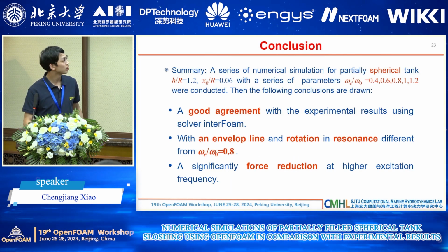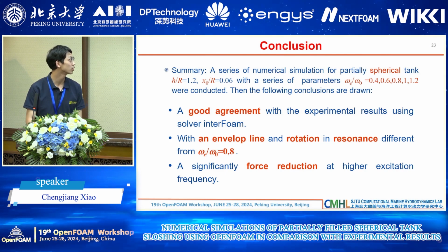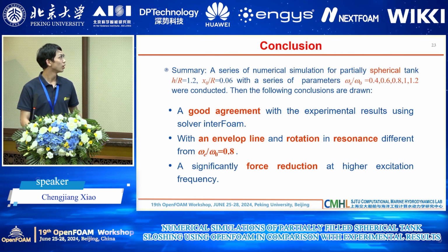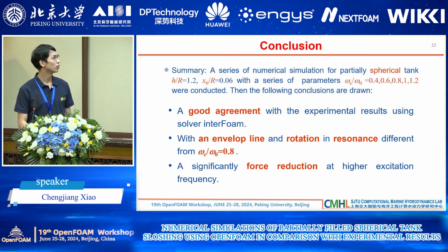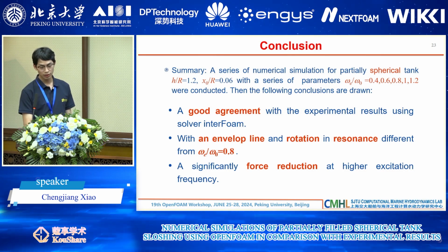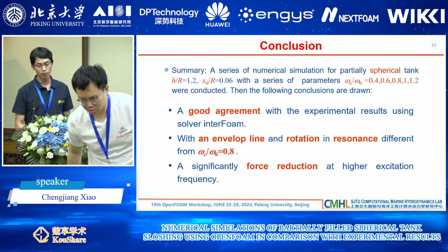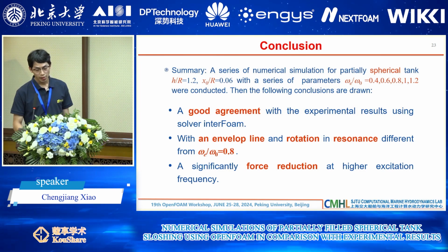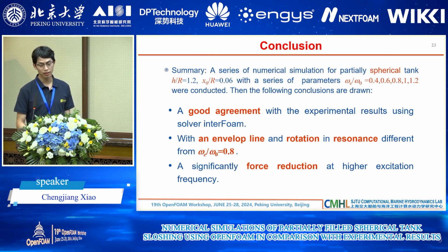Now, in summary, a series of numerical simulations of a partially filled spherical tank with different parameters omega e to omega 0 were conducted, and the following conclusions are drawn. Firstly, the simulation results are in good agreement with the experimental results. The OpenFOAM multi-phase solver interFoam could accurately simulate the sloshing phenomena, including the free damping and the free surface change while sloshing.